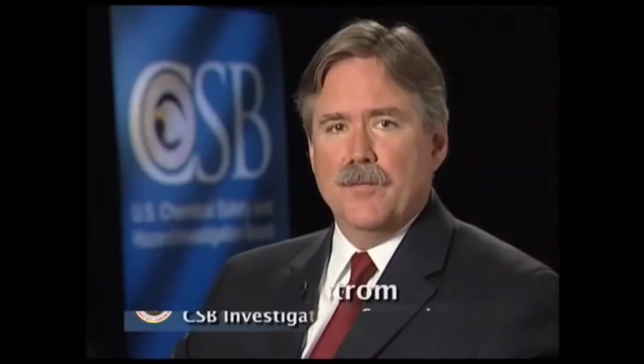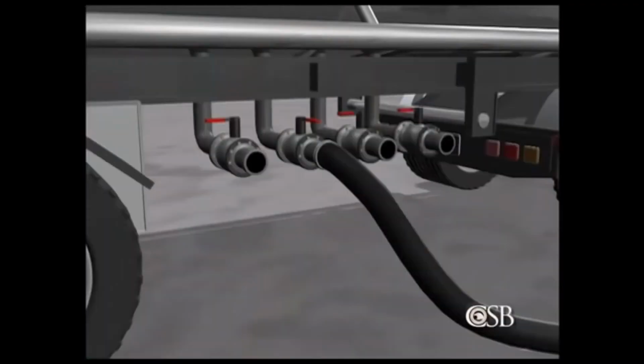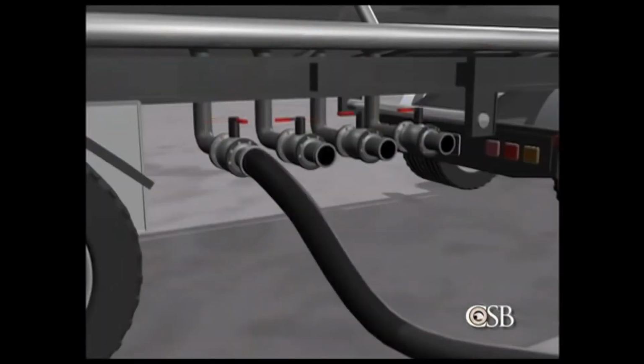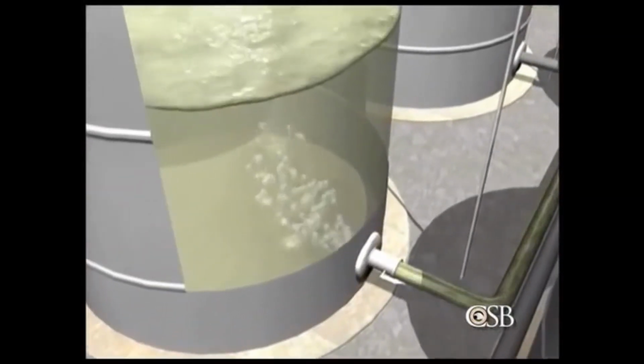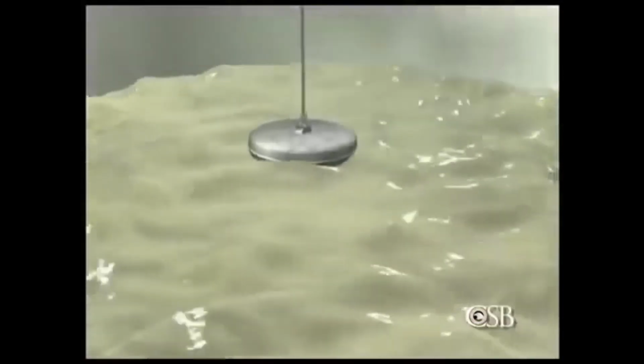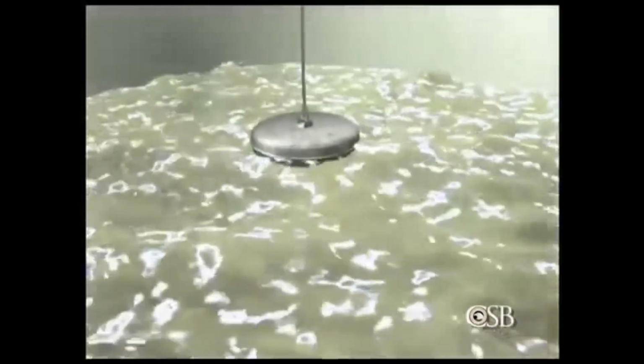When transferring flammable liquids, it's standard industry practice to bond and ground storage vessels, tankers, and other equipment to prevent static discharges. But our investigation illustrates how normal bonding and grounding may not be enough to prevent ignition from static electric sparks. Our investigation found several conditions likely increased the accumulation of static electricity inside the storage tank at Barton. The CSB concluded that repeated starting and stopping of the pump, air in the transfer piping, and the likely presence of water and sediment in the tank all contributed to rapid static charge accumulation.